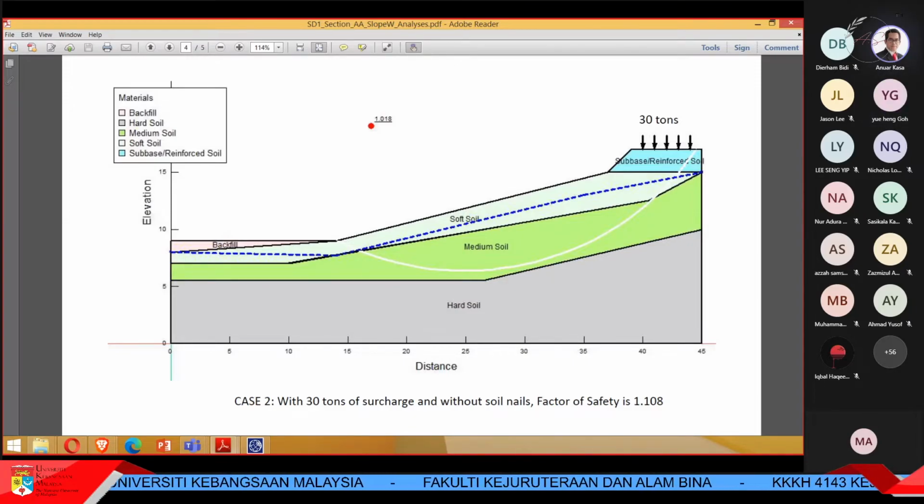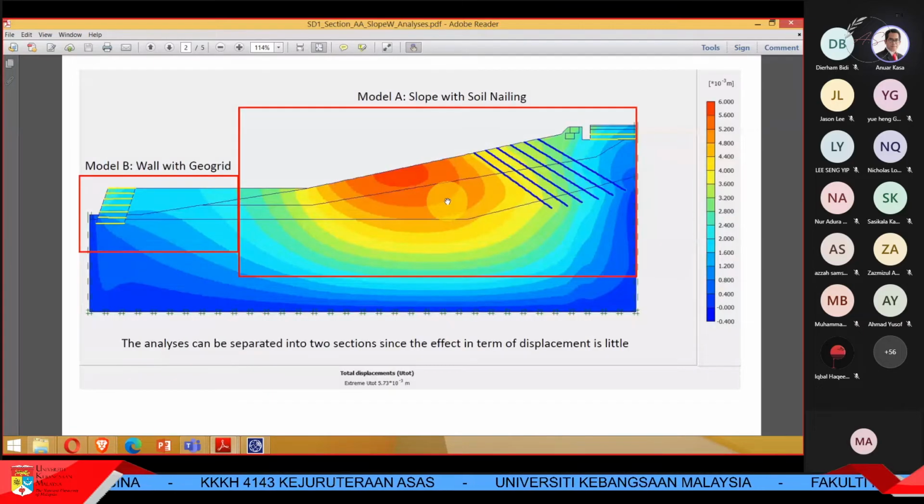Yeah, sure. For the report part, do we need to show manual calculation or not? Just what the doctor said, we only need to do software analysis. I just want to make sure. It is good if you do the manual calculation. Just check the simple one. For example, what is the stress? Easy to calculate, right? Stress equals the depth times the unit weight they are using.